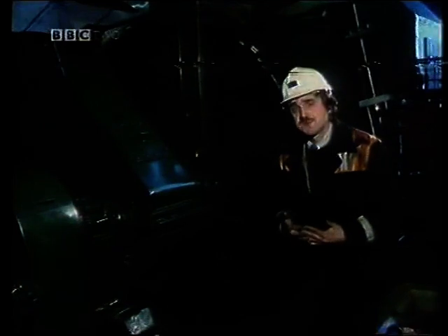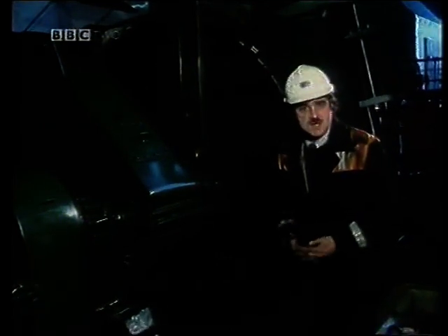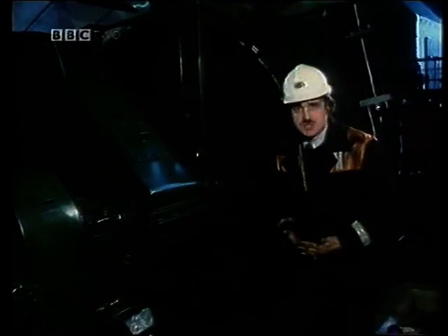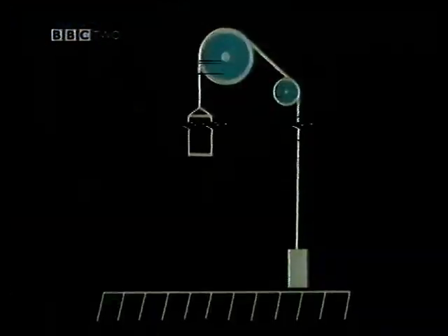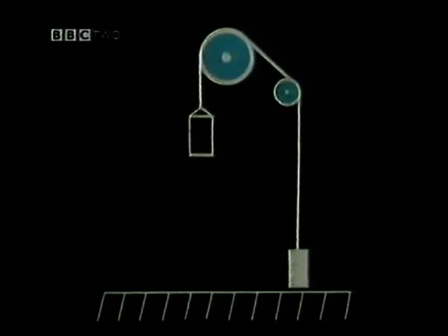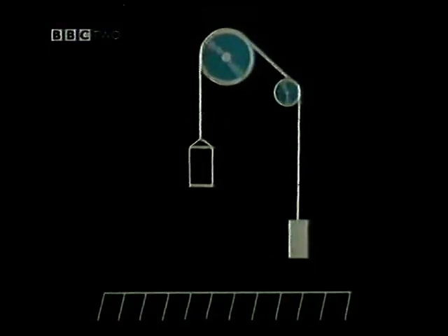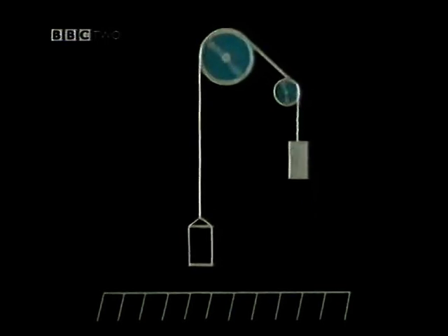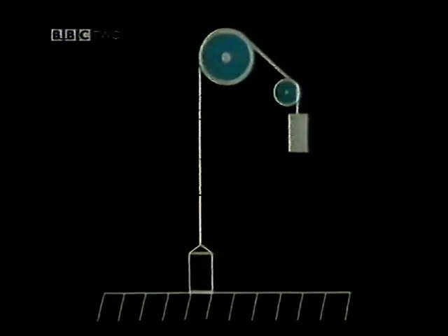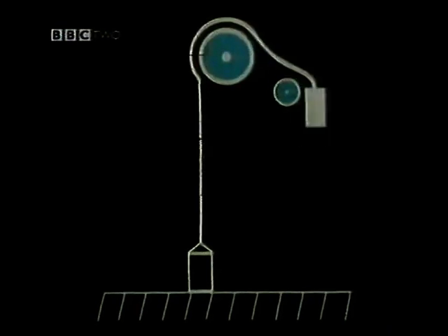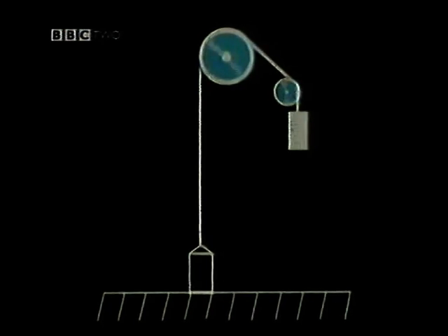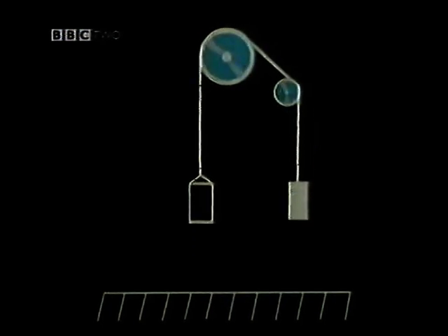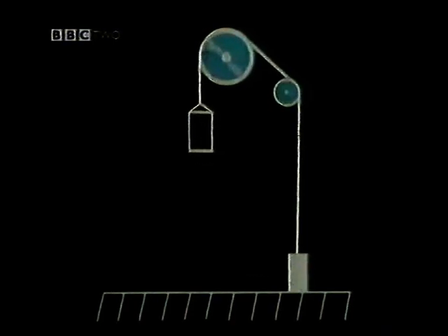So you'll find that in very deep mine shafts, a different drive system is sometimes used, a friction or a traction drive. The traction system has a continuous rope between the car, seen here on the left, and a counterweight on the right. Unlike the drum system, the rope doesn't need to be stored. The rope is just hung over the sheaves. It's the friction between the traction sheave and the rope that provides the required traction. Moreover, if the counterweight bottoms, the traction sheave slips, so the car can't be drawn over the top, a useful safety feature.